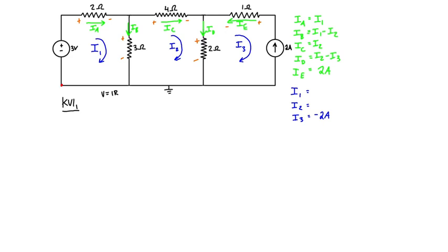And for the resistors here, we don't actually know the voltages, but we can find them in terms of their resistance times their current. So anyways, starting here at the red dot, we're going to enter through the negative terminal of our 3-volt battery. So we're going to start with a negative 3. And then when we enter through the positive terminal of this resistor, we'll assign a plus, and we're going to have 2 ohms times the current, which is IA. Then when we enter through the positive terminal of this resistor, we use a positive value here, and it is going to be 3 ohms times the current, which is IB. And that is all equal to 0.